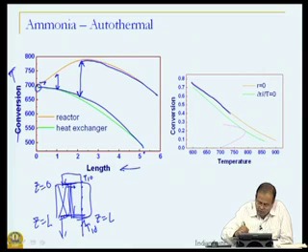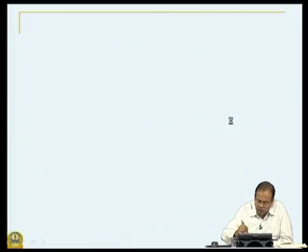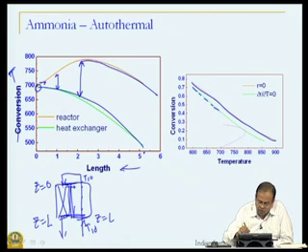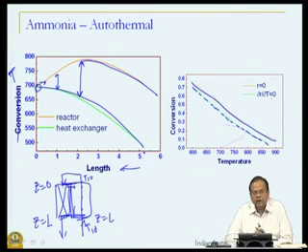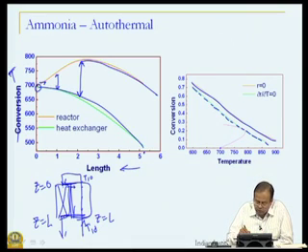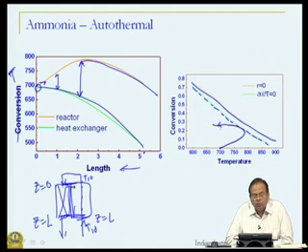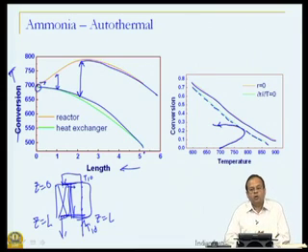This is my equilibrium line, R equal to 0. This is the line for which delta R delta T is equal to 0, and in autothermal operation, if you plot conversion versus temperature, it actually follows this particular trajectory, which is what we wanted by using adiabatic reactors or by various different ways, and this is now very conveniently obtained in an autothermal reactor itself.